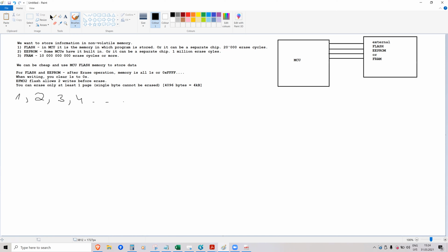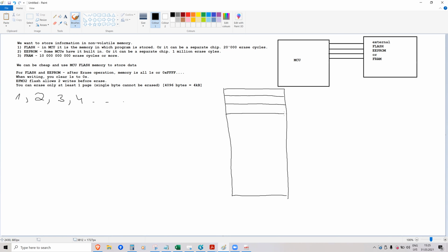So usually how it's done is we take a memory, this flash memory, it has some memory locations. The flash memory inside our microcontroller is organized in 32 bits, but generally you would use an 8-bit memory, and then you just write each part of the number in its own byte.